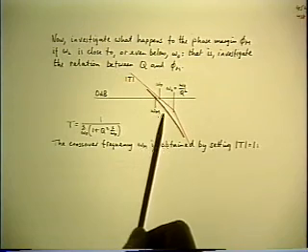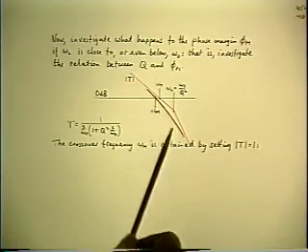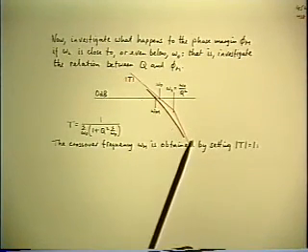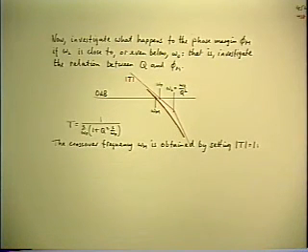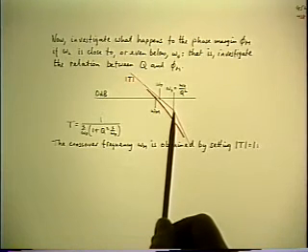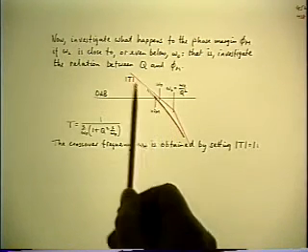Now, this is one of the rare cases where you actually have to account for the smooth curve at the corner, and the asymptote itself is not sufficient. The reason being that we want to allow omega 2 to move through omega 0.